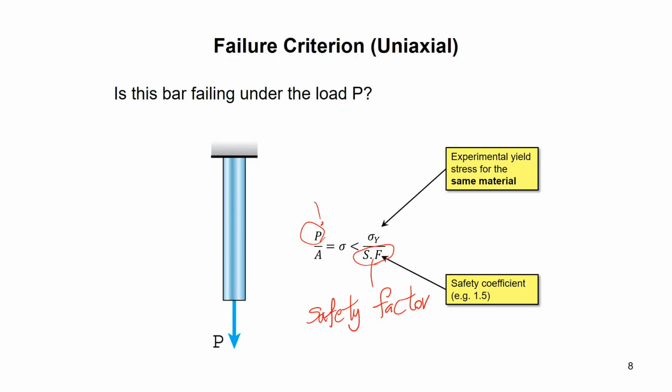And you don't really know how big the turbulence is and how much force it will apply to the wings of your airplane. So if you design the wings so thin that the only force you consider is the lift and the drag and no turbulence, then when a huge turbulence comes, you might see your wings break.